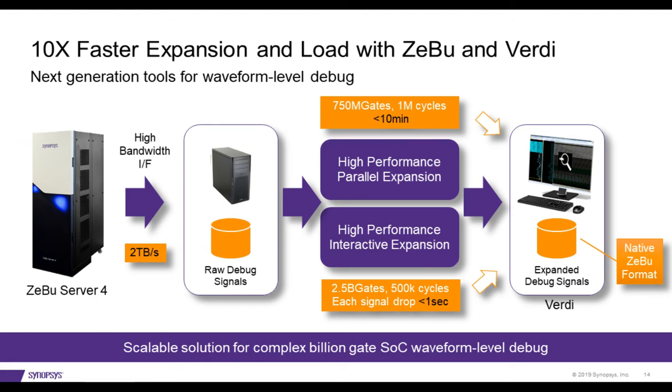We are achieving it through really next generation tools to address the exascale debug complexity. Typically, as we were describing earlier, from the emulator you're dumping raw data of some essential signals, combinatorial signals, and then you're doing the expansion into the full visibility waveform.